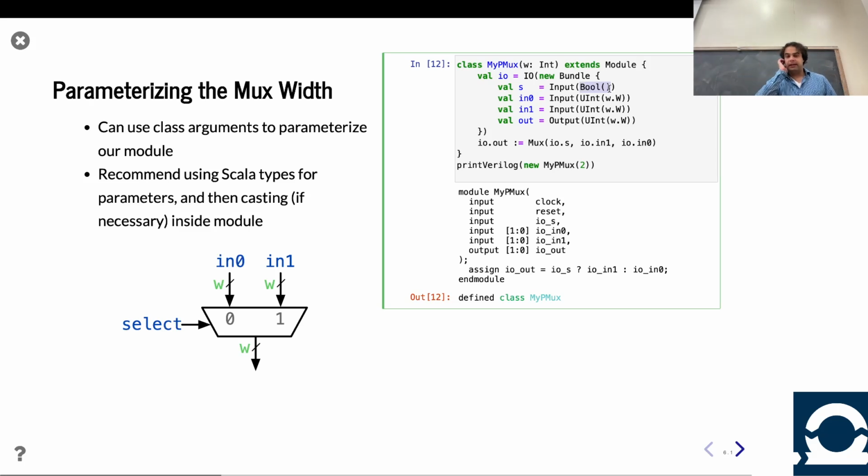Yeah. So the way to think of it is, if you want a multi-bit signal, UInt's the way to go. There are times where you have a collection of bools, like you have n bools. That is totally a valid thing. There's a lot of reasons why it comes up. We'll see that in a few weeks. But typically, when you use a bool, you want that entity to be 1 bit, and you're treating it as 1 bit, viewing it as 1 bit. Technically, in the Scala program while it's running, yes, it's probably bigger than 1 bit. But from a designer's point of view, when you use a bool, you tend to mean 1 bit. If you want more bits, usually UInt's the best way to go.